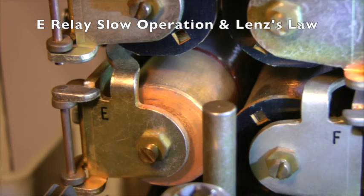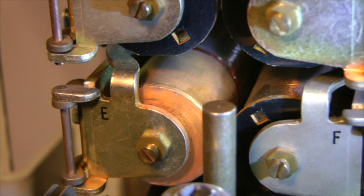The E relay is slow to operate to ensure that the wipers have stopped vibrating and won't snag before rotary stepping begins. The slow operating feature is accomplished by the use of this copper slug at the armature end of the winding spool. The copper slug enables the application of Lenz's law.